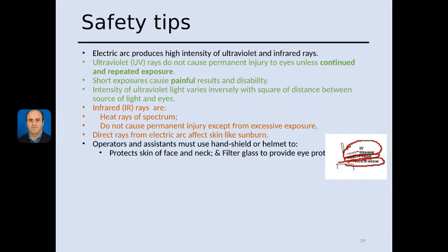We have seen many welders who do not cover their neck during the arc welding process, and the neck has some burning effect. That is one of the safety concerns in arc welding processes. So the neck or the skin has to be covered so it doesn't get burned.